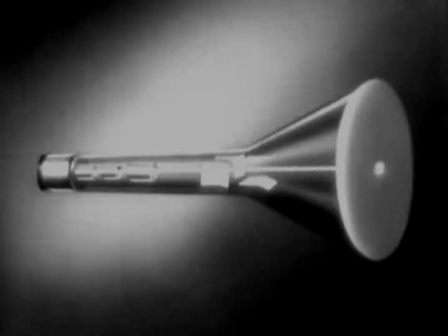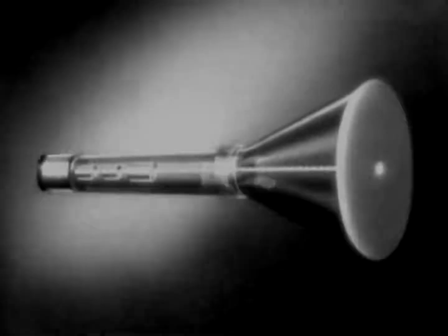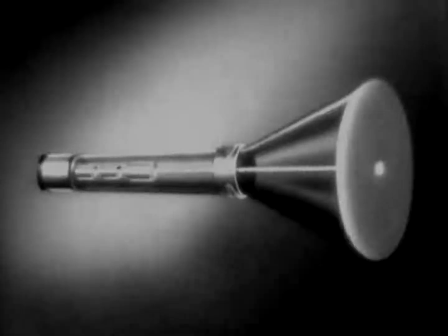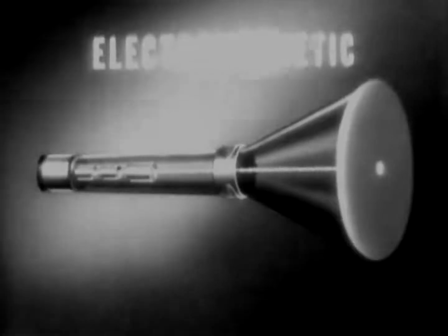In developing this PPI scope, a new type of cathode ray tube had to be worked out. In order to project both range and azimuth at the same time, the deflecting plates inside the tube were replaced by a pair of coils around the neck of the tube on the outside. This is the other type of tube we mentioned earlier, the electromagnetic cathode ray tube.